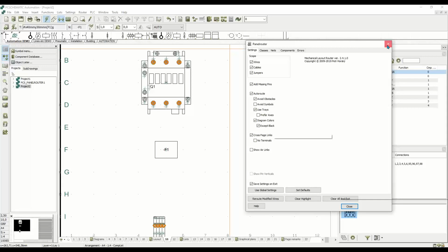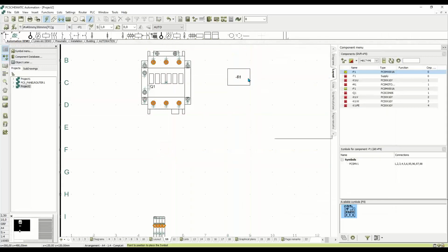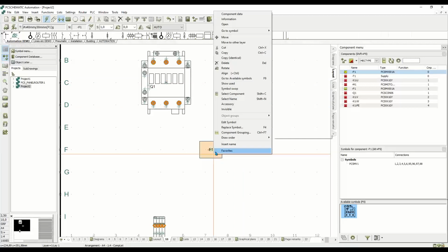But you can see that if my components would be up here and I would go from this and I would do like that, and I would have some other wires going from the bottom, then if all wires were routed to the middle, some of them would definitely be wrong. So it doesn't work in that way. It's simply because it's got the wrong component group, so it doesn't recognize it as the same component here. That's the reason why it doesn't work.